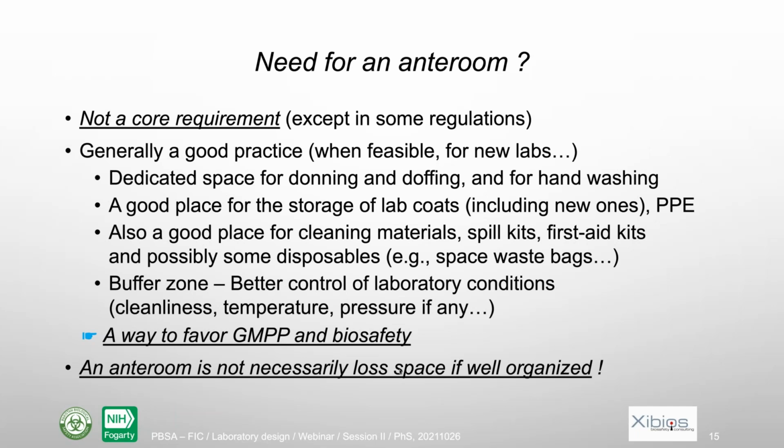And then it's also a buffer zone which helps keeping good laboratory conditions. So in having an anteroom, it will be easier to keep a right temperature and humidity in the room. It will not be so easily influenced by the corridor, for instance. And so it's really a good way to favor good work practices and biosafety. So when it is possible, because you are thinking of new labs, you could really opt for such control measures.